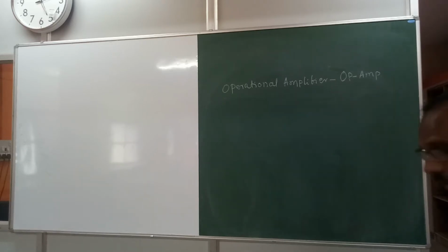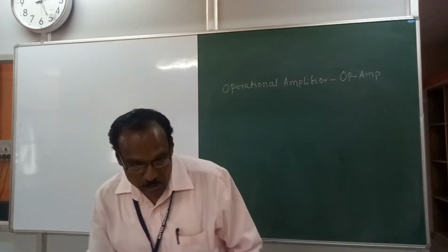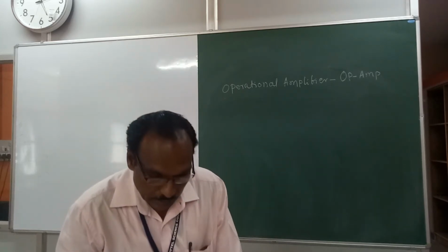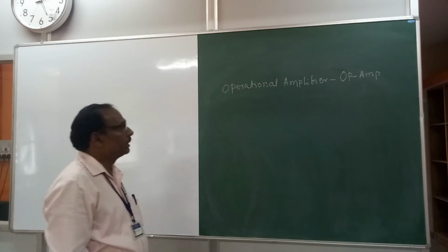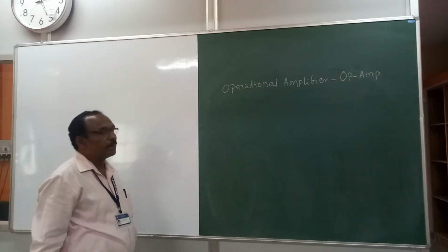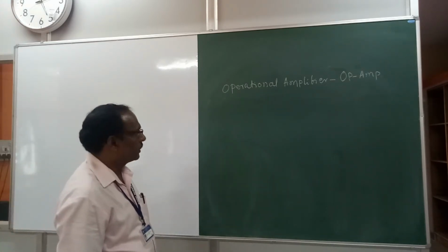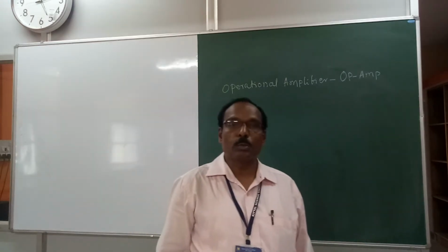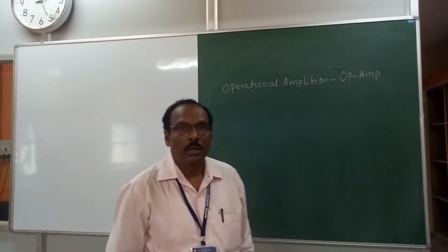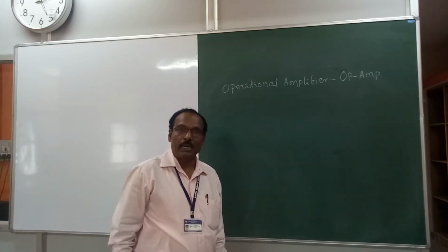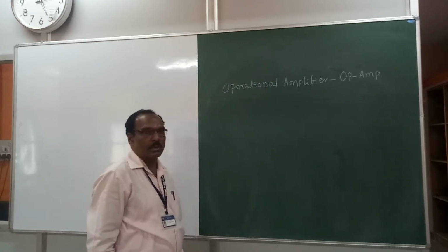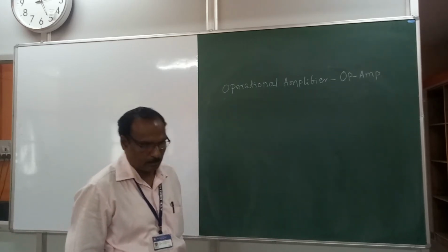Fine. So, an operational amplifier is a high gain, direct coupled negative feedback amplifier with high input impedance, low output impedance, with feedback added to regulate its frequency response.